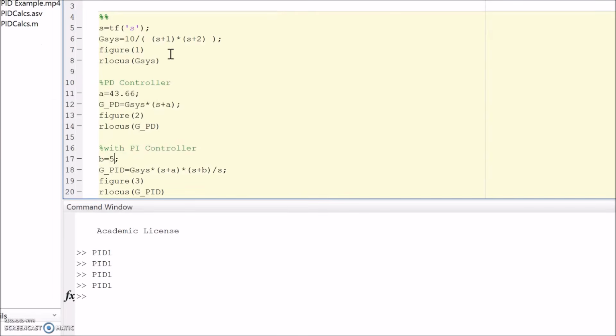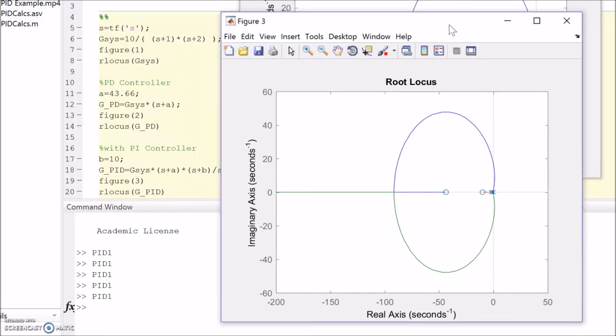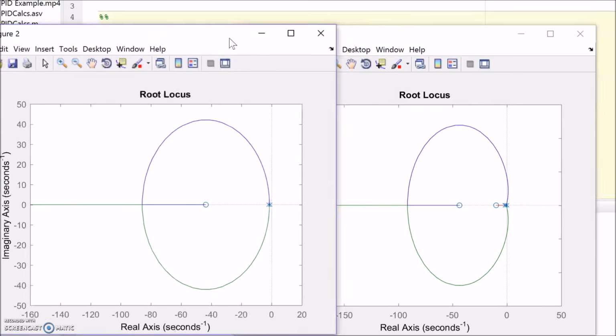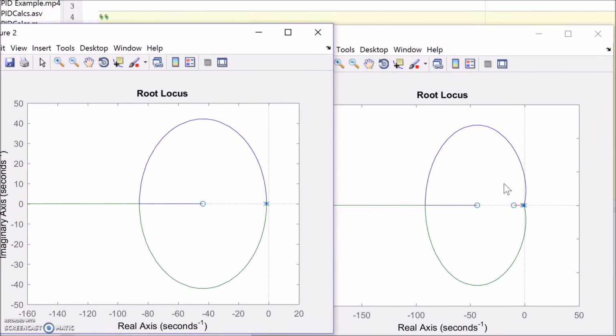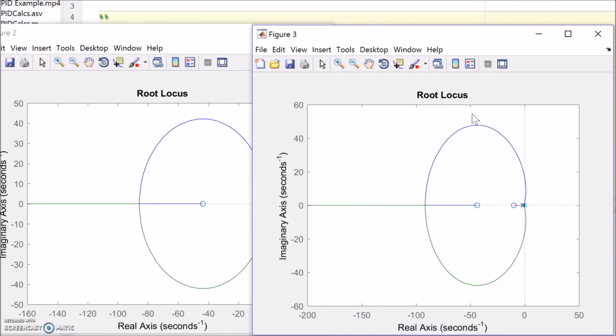But I don't know, let's say we push it even more and make it like 10 or something like that. And have a look at what the change is. You can see that this one, yeah, definitely looks not so good. Yeah, it's starting to bulge more and more around these points, which means that we're also probably getting a bit of an impact up here. So our desired pole may not necessarily sit on our root locus anymore. So yeah, we haven't really achieved that pole 0 cancellation that we were looking for.